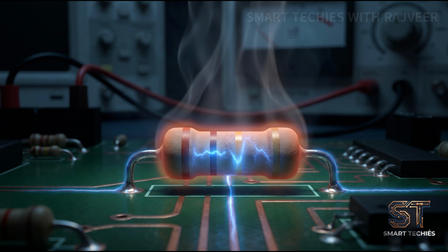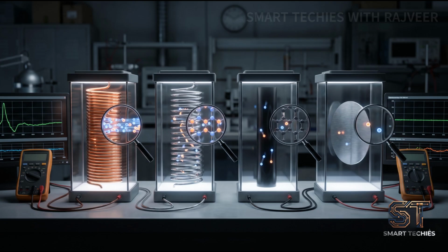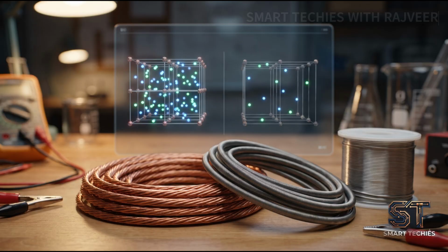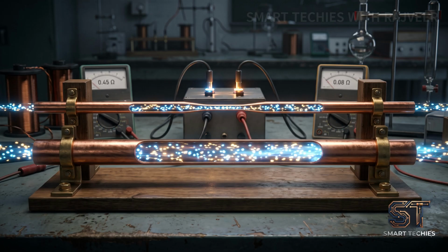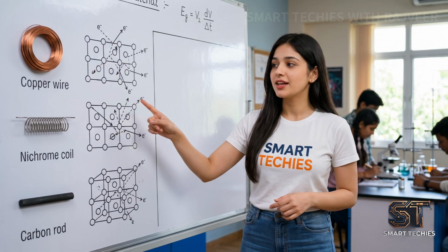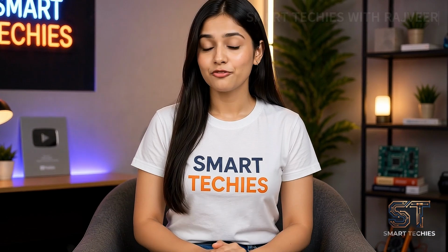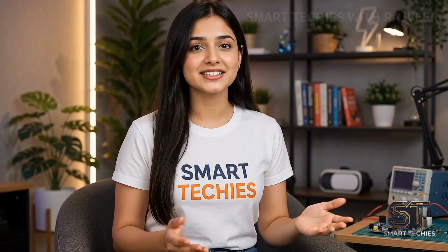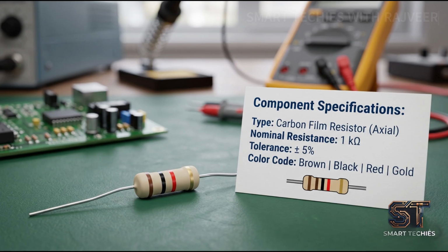Here is another important concept. The resistance of a material depends on several factors. One of them is the material itself. Different materials have different electrical properties. Resistance also depends on the length of the resistive path. Generally, a longer path gives higher resistance, and a thicker path generally gives lower resistance. The relationship can be written as R equals ρ multiplied by L divided by A. Here, ρ represents the material's resistivity, L represents length, and A represents cross-sectional area. This principle is very important when resistive elements are designed.